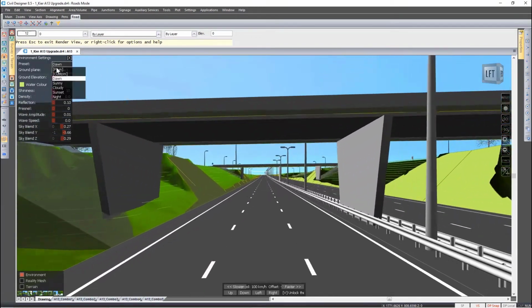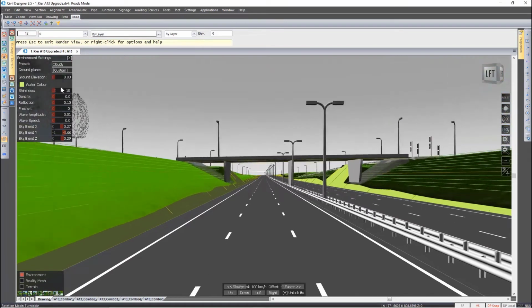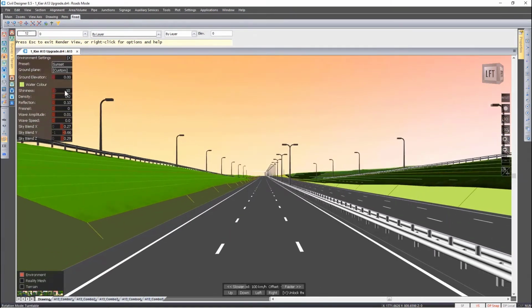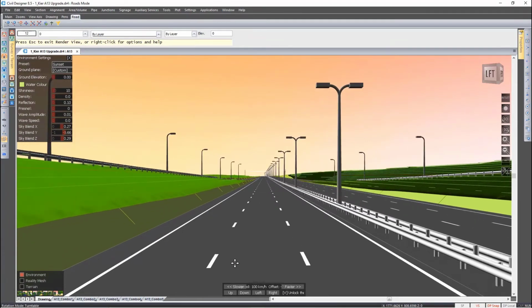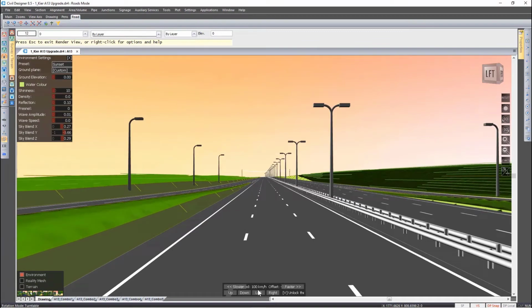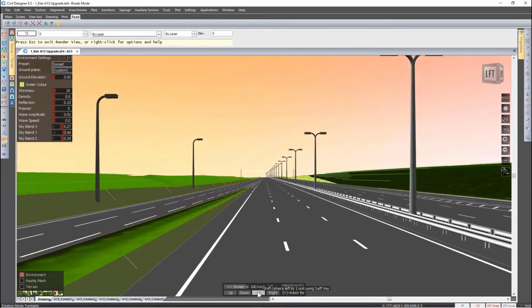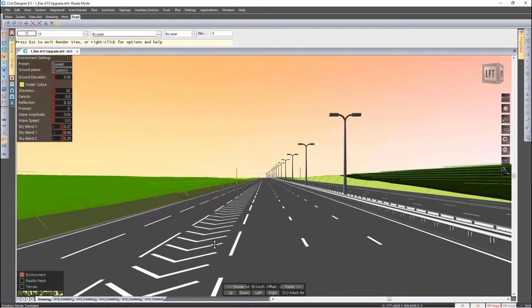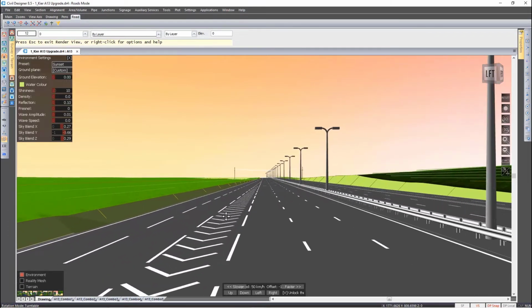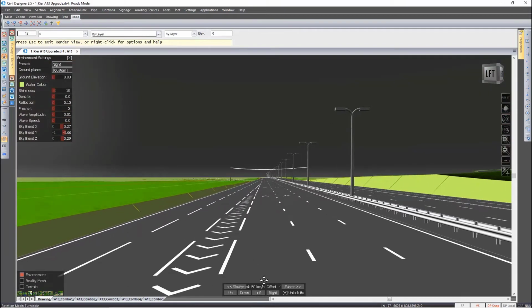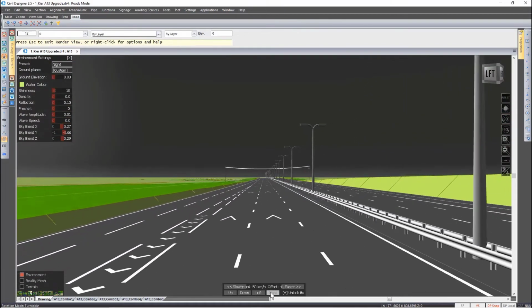Carrying on with our environmental settings, and as we approach this on-ramp onto the highway, these road markings can now easily be inserted by using the new Drape hatch functionality found under the road's signage menu. Changing my environmental settings and moving to the right.